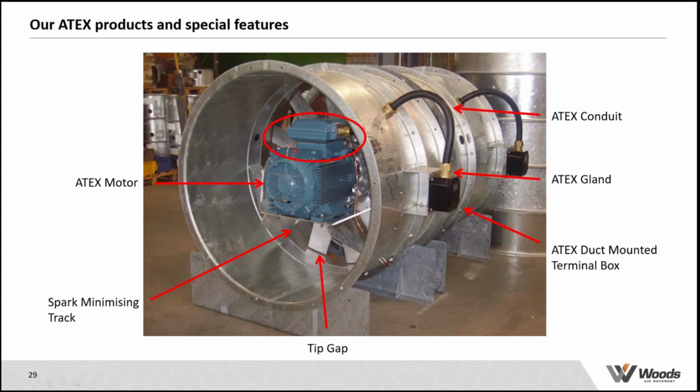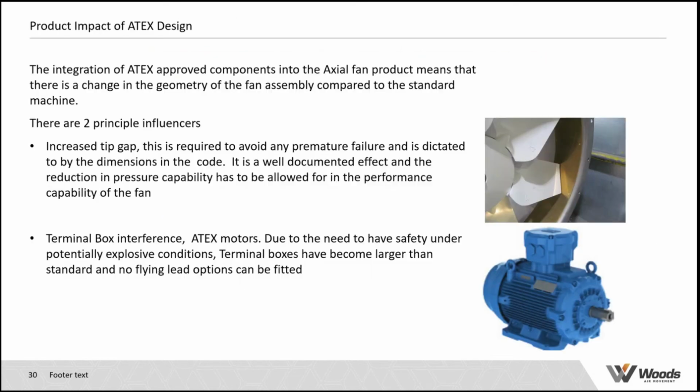The other thing that doesn't show here is that on the impeller, there's a secondary fixing device, which means the impeller cannot shake loose. Because obviously anything that risks having a contact, we want to avoid. For dust, for the higher group of dusting, you would also put vibration sensors on the fans, because obviously one of the risks with dust is that there's a build-up of dust, goes out of balance, maybe causes some sort of failure, bearing failure, the impeller drops, hits the contact. So yeah, that would be covered by that.